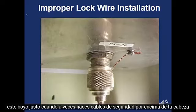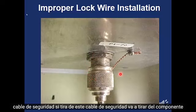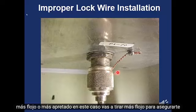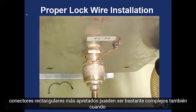When you safety wire things above your head, sometimes it can get a little confusing. Here, notice this is improperly installed safety wire. If you pull on this safety wire, is it going to pull the component looser or tighter? In this case, you're going to be pulling it looser. Make sure that you switch around the safety wire so that instead it's pulling the connector tighter.